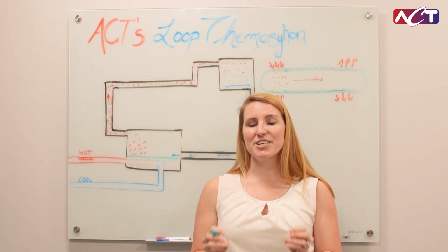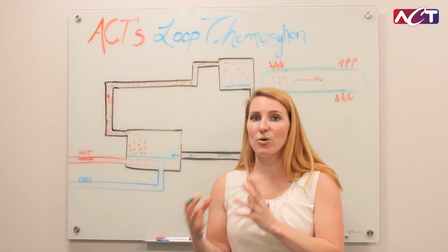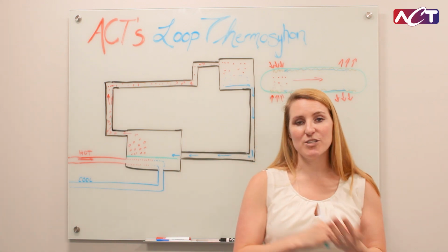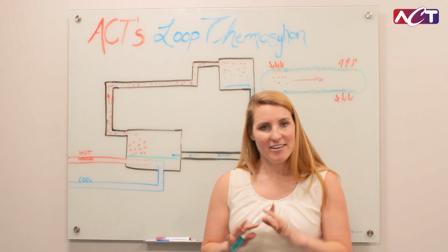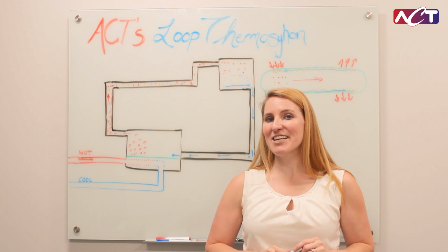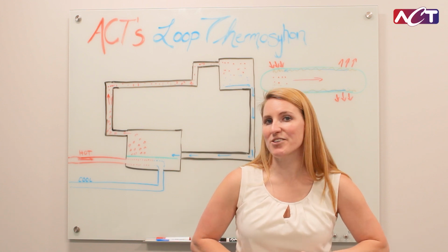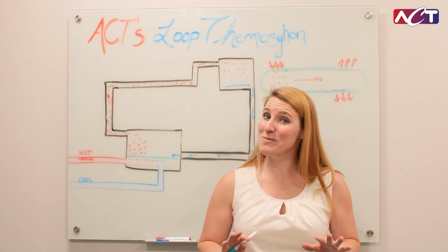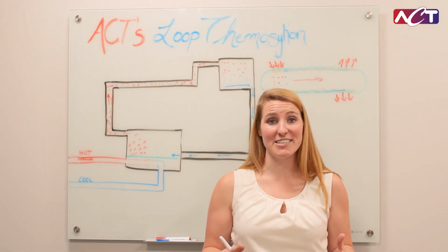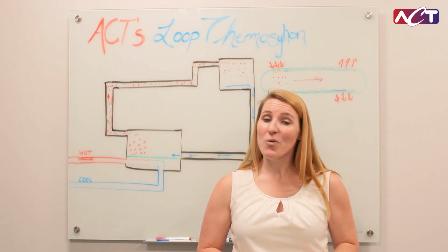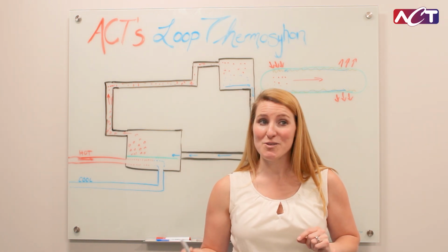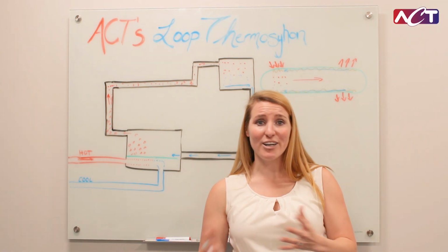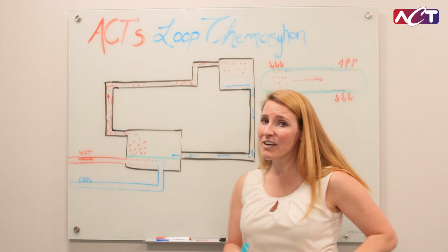Now, the latent heat of vaporization is awesome when you look at the working fluid. It's the amount of thermal energy it takes to convert from a liquid to a vapor phase. Water's latent heat of vaporization is 2,257 kilojoules per kilogram. That's compared to its specific heat, which is the amount of thermal energy it takes to raise it 1 degree C, which is 4.187 kilojoules per kilogram degree C. So that's very significant, going from 4 to 2,000. And that's what we're leveraging here.